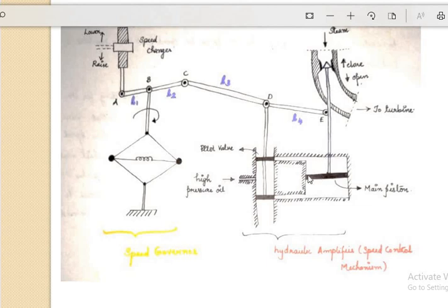And there is a pilot valve. Here you have a pilot. This is one valve. This is yet another valve. Here some high pressure oil is falling into this area. Under this position these two valves are closed. See, this is one piston. The piston has two parts. Currently in this position these two valves are closed, so the high pressure oil is there within this.